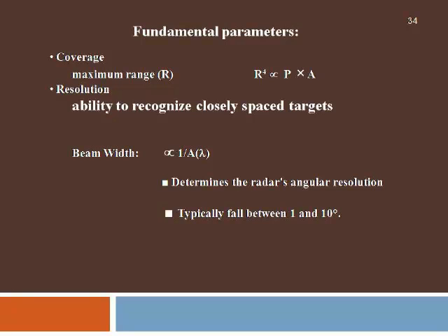The minimum signal is a very strict constraint on the receiver, and if this signal is very low, the cost of the receiver is going to increase drastically. So the antenna must be able to give a sufficient amount of signal by providing a high effective area.